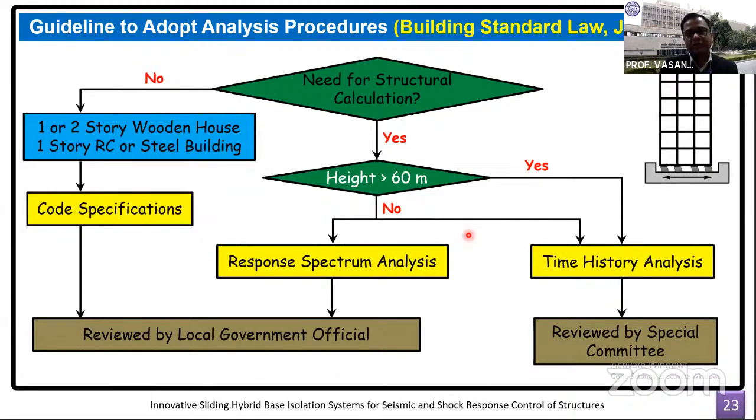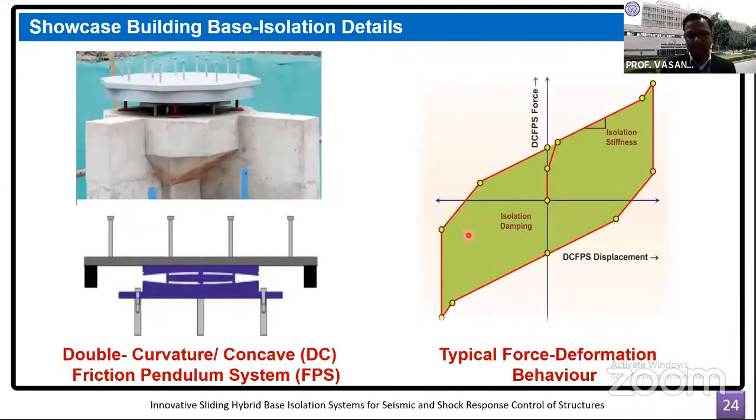So in this project, we decided to conduct the nonlinear time history analysis as well. And we were involved in the modeling process of the highly nonlinear isolation system and its equivalent linearization. What you see in this picture here is the isolation system that has been used in this project. It has two curvatures here. This is the upper curvature and this is the bottom curvature, same curvatures, which helps us in reducing the size of the isolator, whereas the time period elongation can still be obtained.